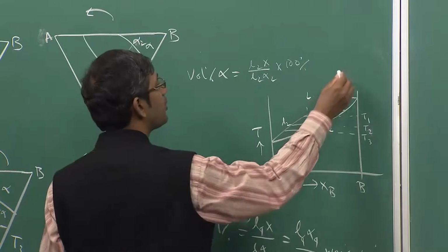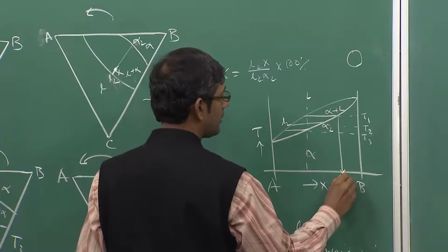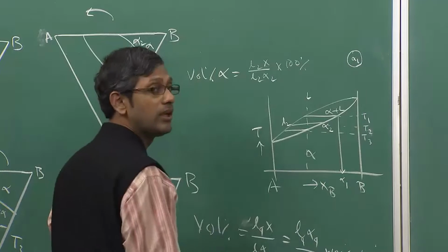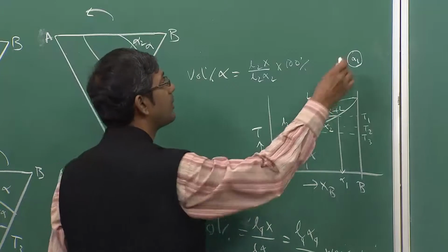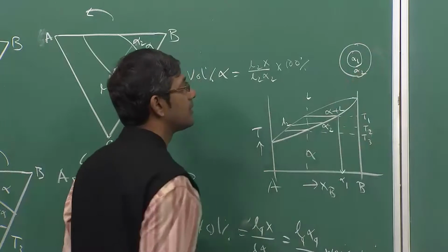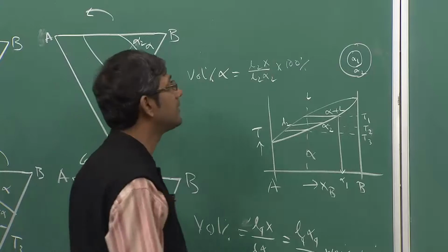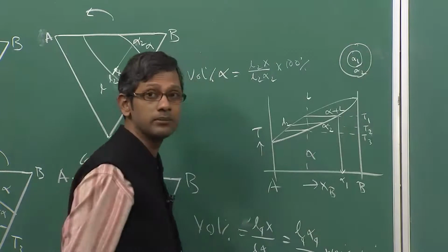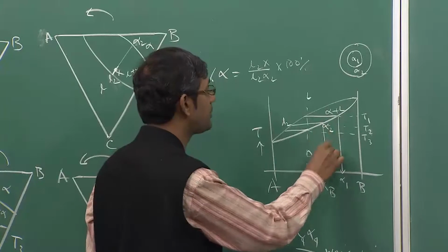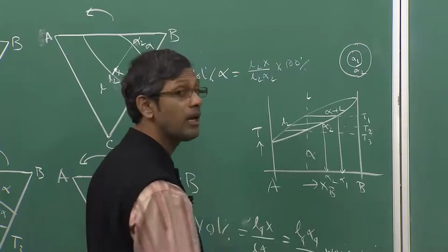So, whatever solid I form at T1 will have compositions given by this point. Okay, so I write down alpha 1. As I cool it down from T1 to T2, I form another solid layer with the composition alpha 2, correct. The problem in the non-equilibrium case is that you do not provide enough time for these two solids to homogenize, because these two solids have different compositions, right. Can you see? Alpha 1 is richer in B than alpha 2.